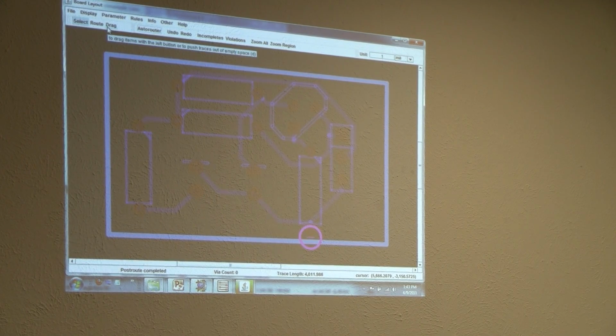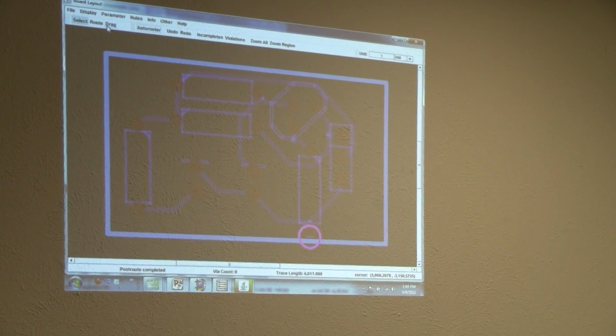There is some capability for you to do some things, but most of the boards that I deal with, which are fairly simple, I just don't. Every time I've done that, I've found it harder than to just hit undo and go back to KiCAD, move the part a little bit, and go that way.